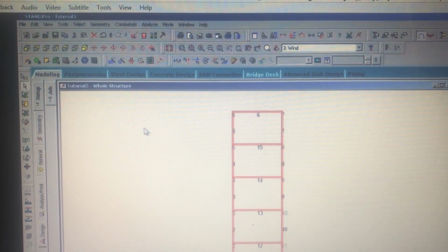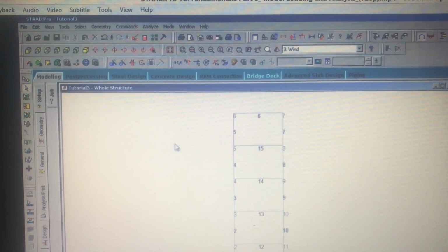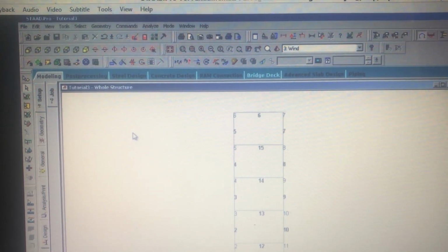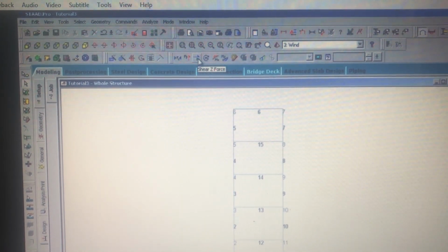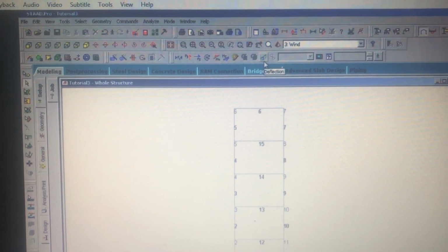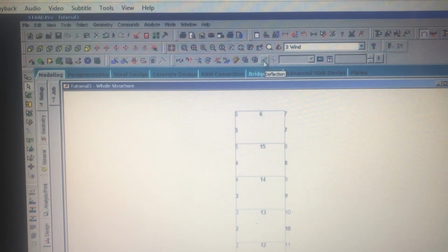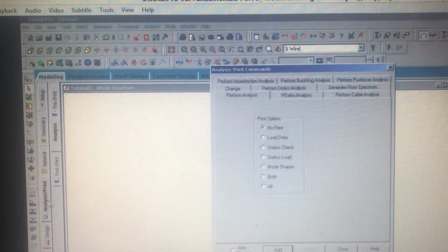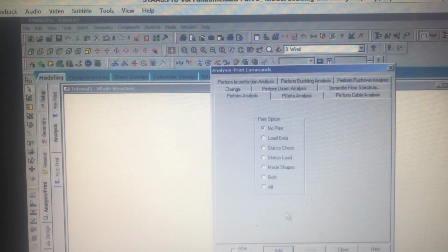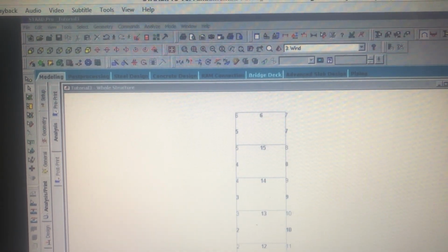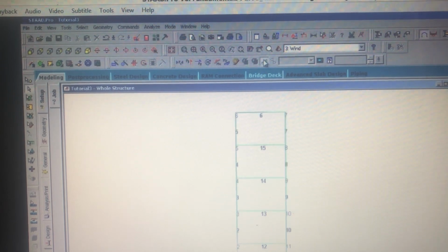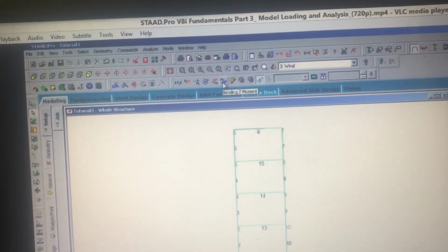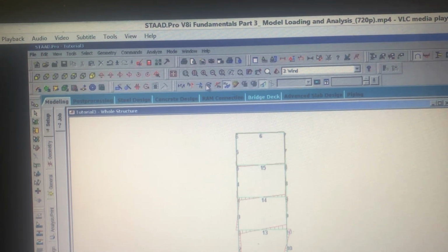Now we can see, I would click here to deselect all the beams. Now we can use all these options here: axial force, shear force, the bending moments, the deflection. We can use these diagrams only because we had chosen this all print option here, so that we can stay in modeling mode and then choose deflection, or maybe the bending moment diagram here, or anything we want.